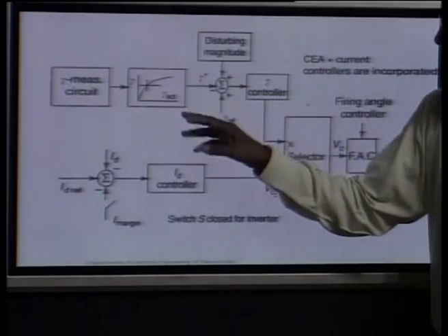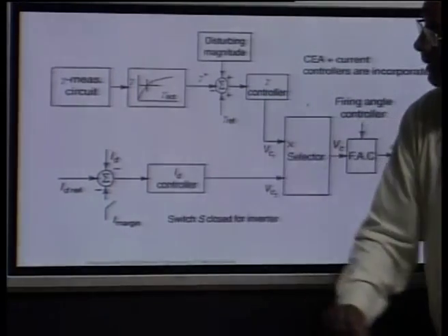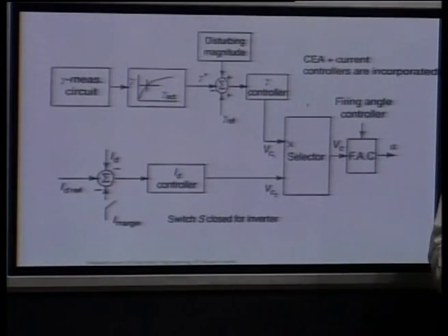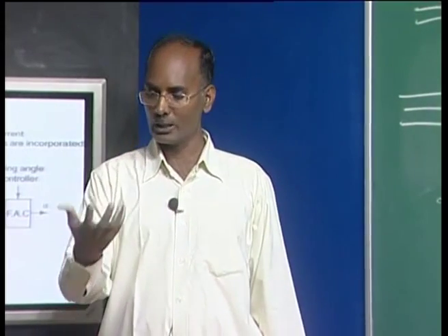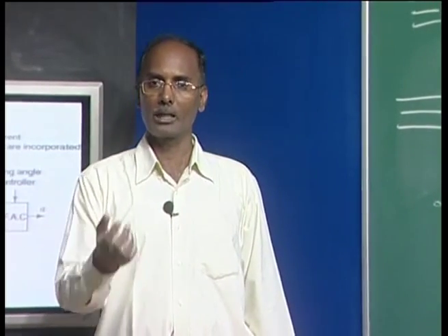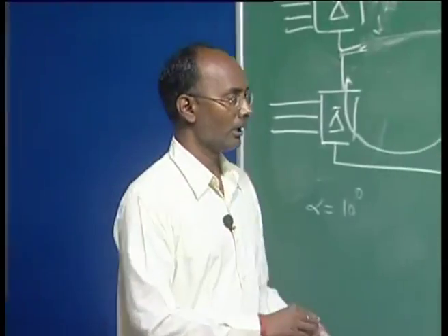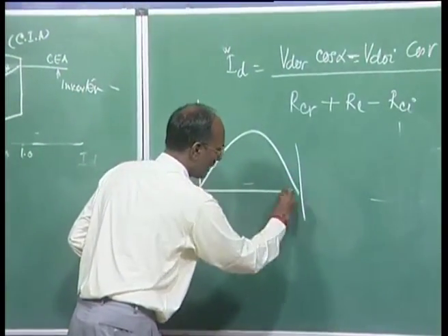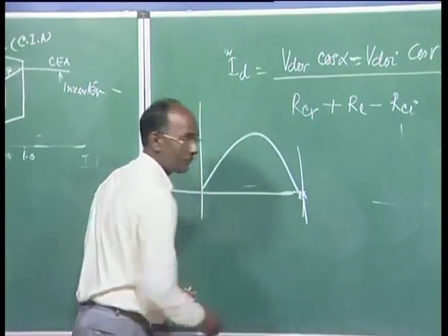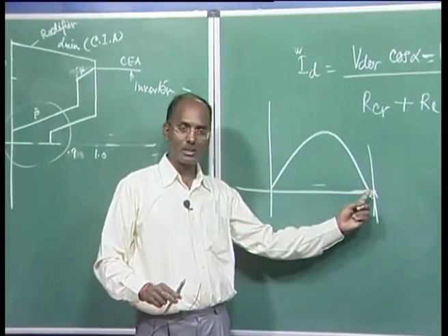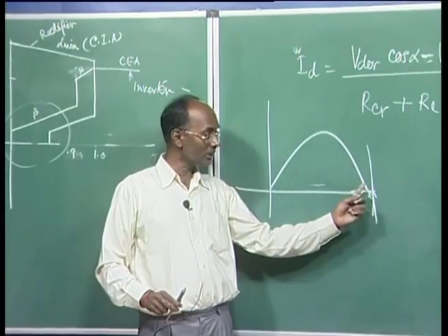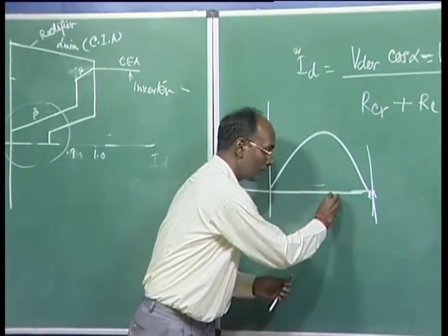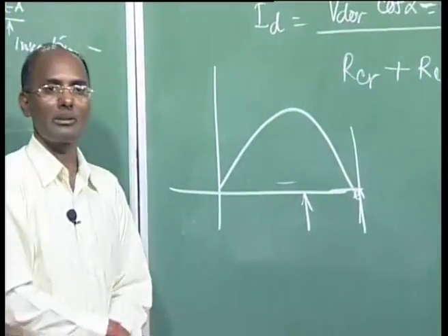On the inverter side, we have the gamma measuring circuit. Now you can ask how you can measure gamma. We are visualizing it with a circuit because we always require some zero crossing here. This is how the zero crossing is calculated. Because you are calculating now, you cannot estimate the zero crossing ahead.